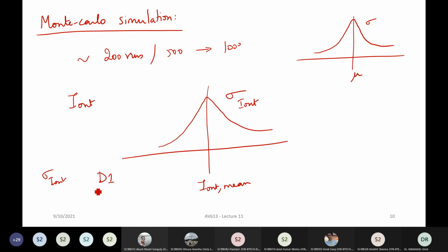Okay, let's say your design one had W equal to 5 micrometer and L equal to 180 nanometer, and you are not happy with the sigma. What will you do? Design 2, where you keep the W by L ratio constant, but you scale up the W and the L. Let's say you increase it by 3 times, you get 540 nanometer and 15 micrometer.